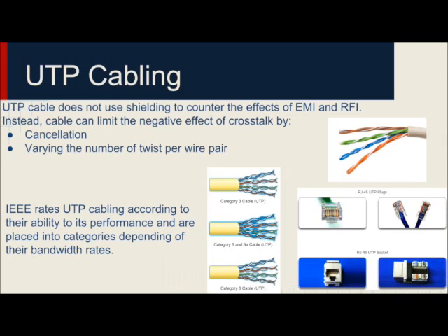The Cat5e supports 1000 megabits per second. Cable Category 6, used for data transmission. An added separator is between each pair of wires, allowing each to function at higher speeds. It supports 1000 megabits per second to 10 gigabits per second.